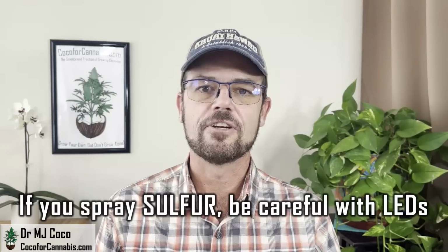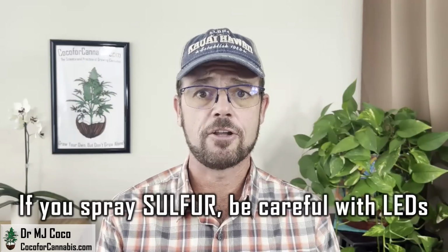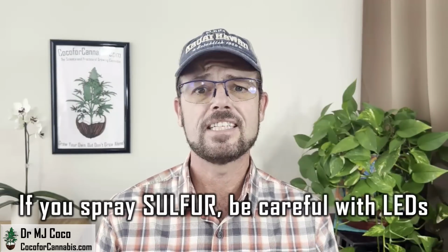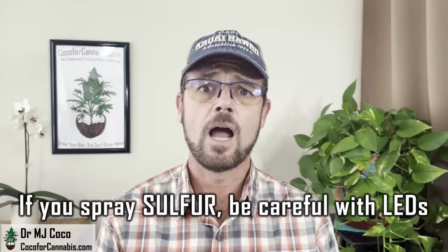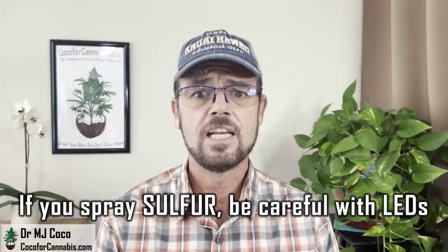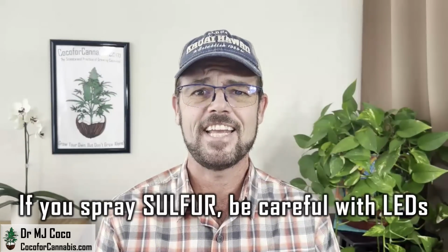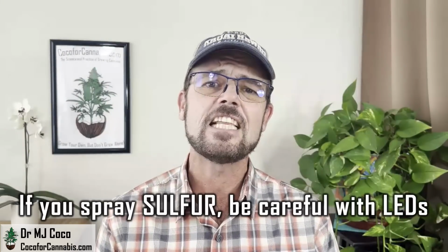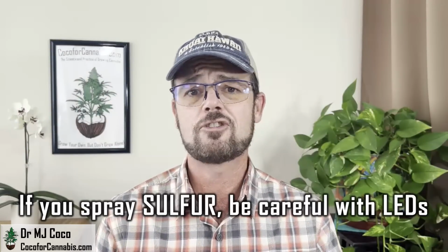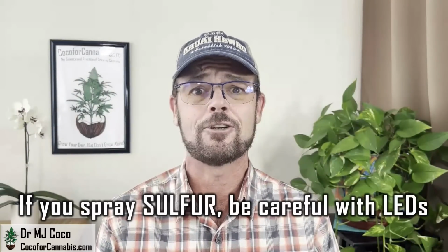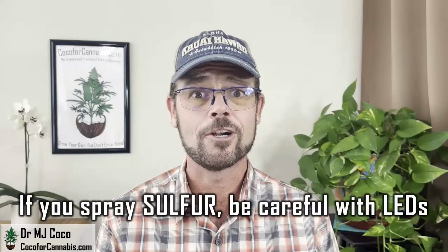Horticultural diode manufacturers are aware that we sometimes spray sulfur, so they go to considerable lengths to fortify their diodes against it. Sheldon sent me an entire file about their anti-sulfur measures, like using gold plating and wiring on their horticultural diodes. But still, he suggests being very careful when using sulfur, and please don't get it on the LEDs. The best practice is to physically remove LEDs from the grow space while you're applying sulfur sprays. It was striking to me that this was something that diode manufacturers are very concerned about, and I think most growers have no idea. Spread the word.